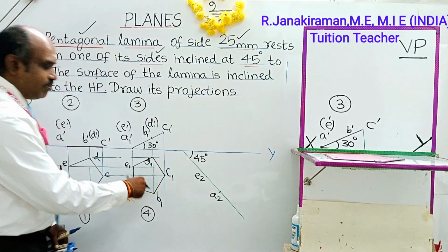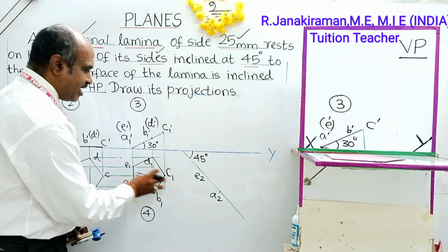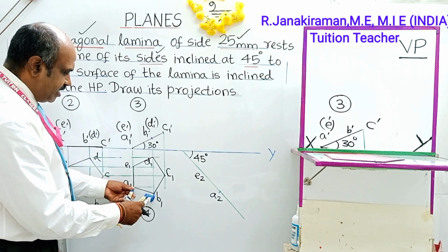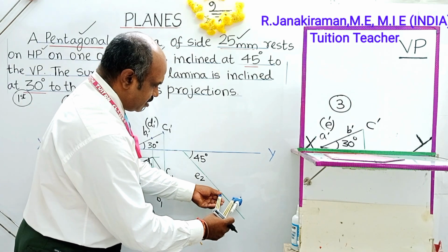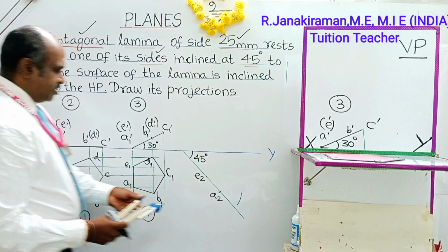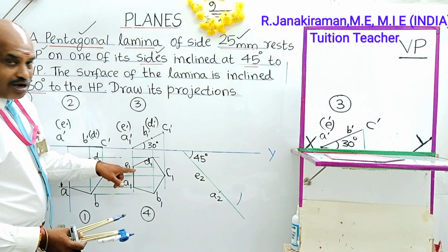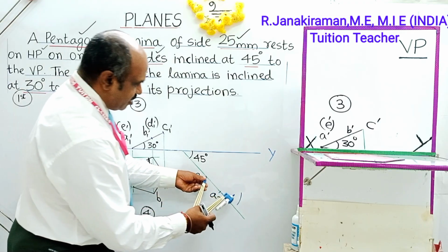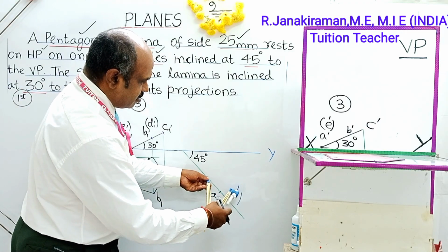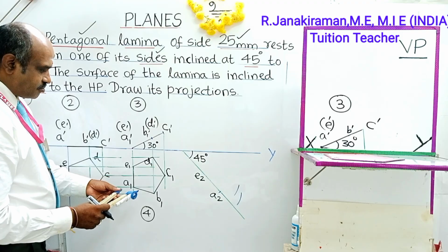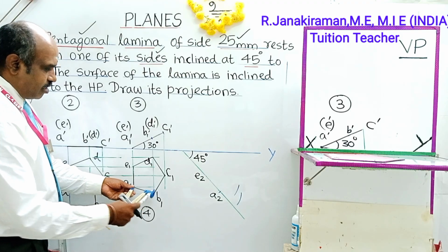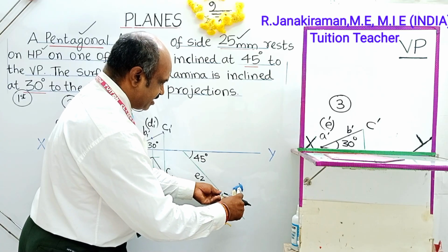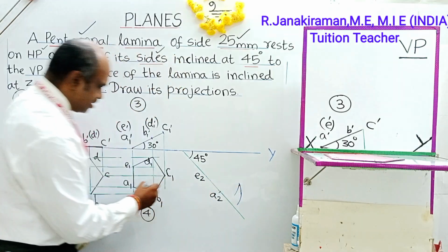This diagram is to be copy pasted. Instead of being like this, I am going to tilt this to an angle of 45 degree. Next, AB distance is taken in the compass. Cut an arc on this line. Next, E we know previously. Take EB distance in your compass. Cut an arc on this. So you have to extend the arc. AB distance is taken in the compass. The point of intersection is marked as B2.